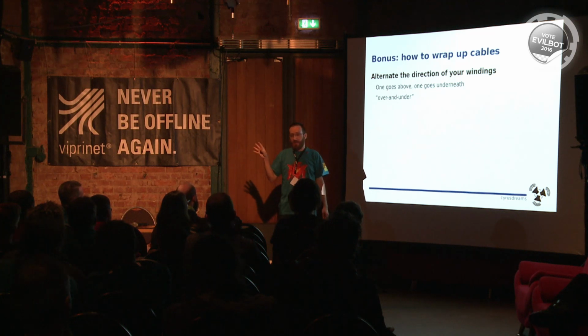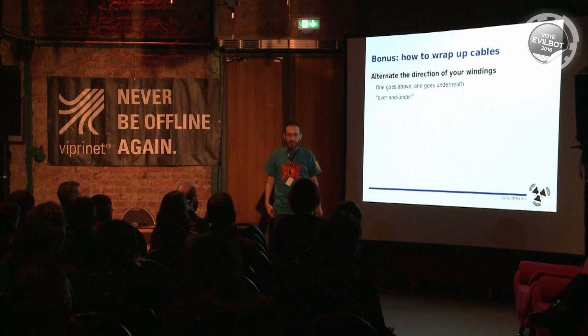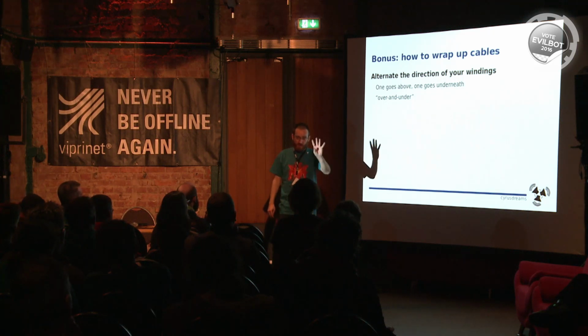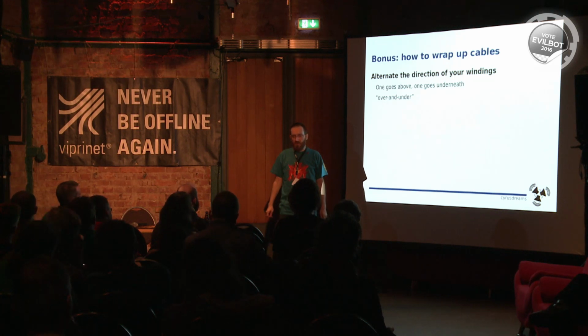That one ends up at 15 or 20 meters. The SDI cable length from here down to the main hall is, we used, how many meters did we use? I think 50 meters, no problem. The propagation on this cable is so good compared to the HDMI, and it's full HD that we transferred down there. And I think we can get 100 meters.